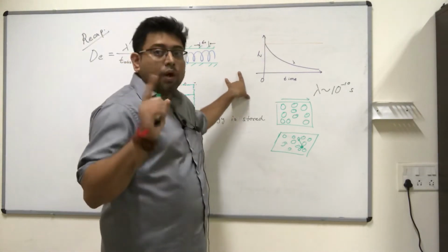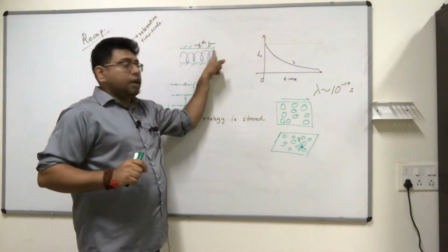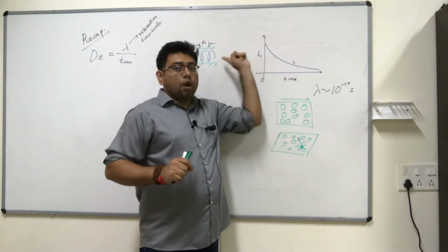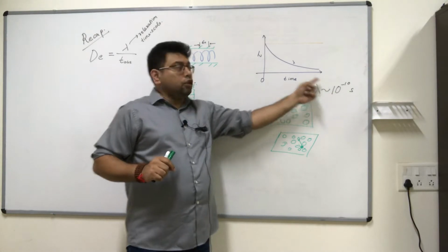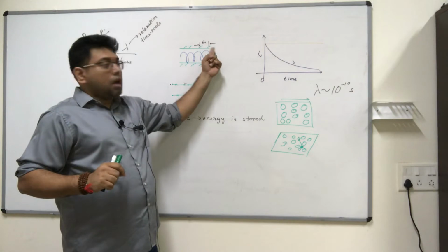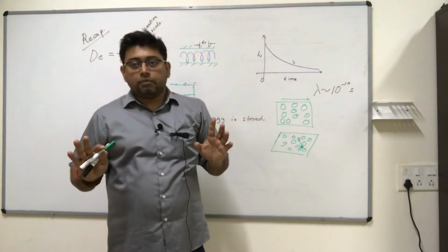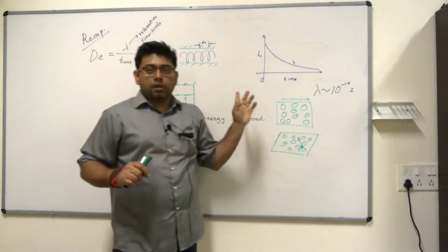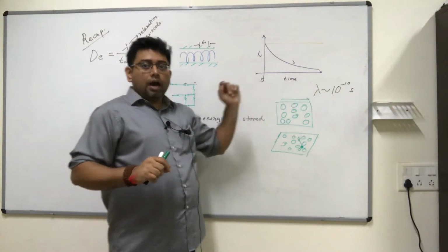Now, one more thing. You applied a strain, and then the stress required to hold it at this location has gone down to 0 for a fluid. So you did some work in displacing this, but what is the final state? In the final state, there is no stress in the system. When you began, there was also no stress in the system. So the energies at the end and the beginning are the same.